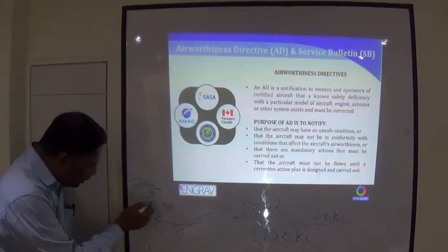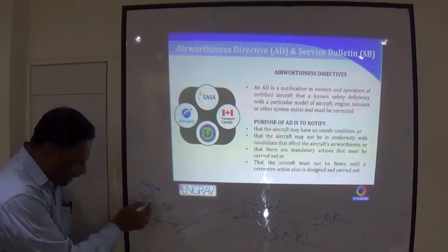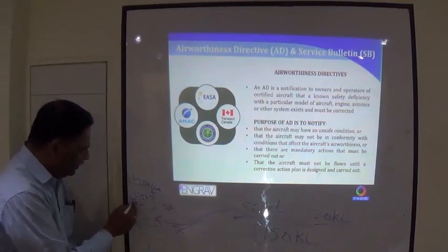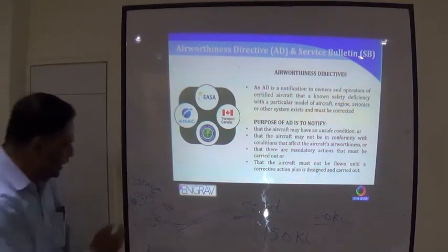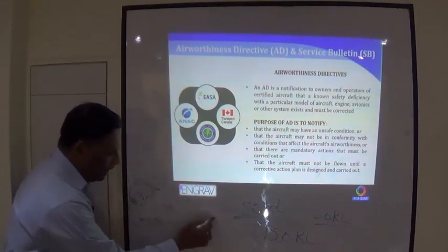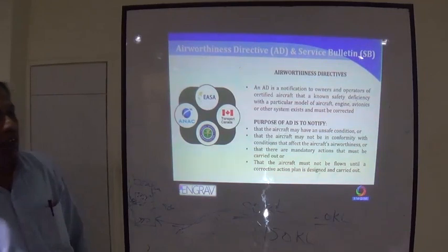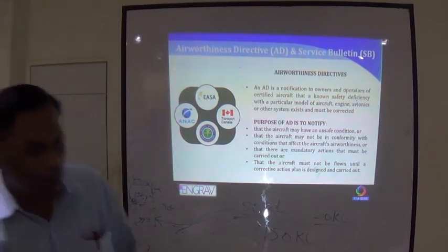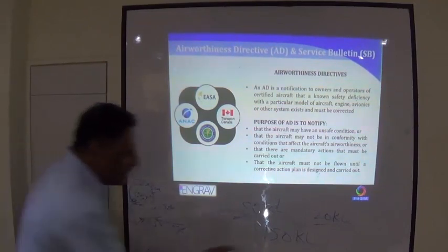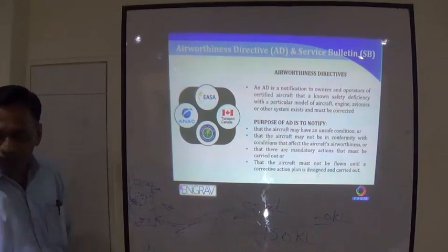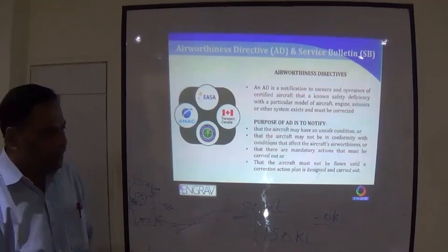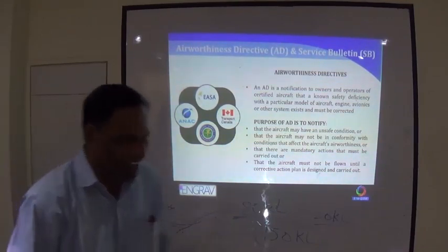Then you take it into the next tank, and then you put a salinometer here. It's all in the system. If the salinity is more than the drinkable permissible limit, again it comes back through another line. If it is okay, you take it into the freshwater tank. In this way, every day we used to generate around 5 kL by the main engines and 5 kL by the generators. So you have 150 kL, otherwise 150,000 liters of water, and you have around 100 people on board. Three meals when you cook for 100 people.